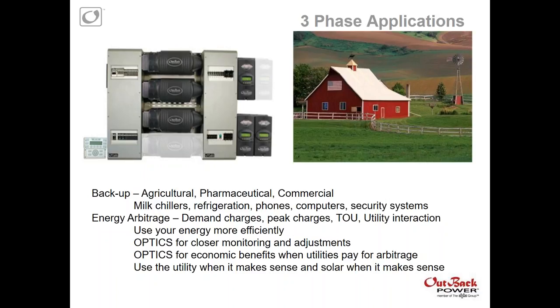So today, this may just be a backup system. You may have time of use, let's say, and it may be a high enough priced tier in the mid-afternoon that you decide you're just going to take most of your facility off the grid for 3-4 hours in the afternoon and then go back to a backup system all the rest of the time. For that matter, you may have a demand charge that you want to get rid of, and you can tell our system to limit the demand that it sees from the grid to a certain number of amps.